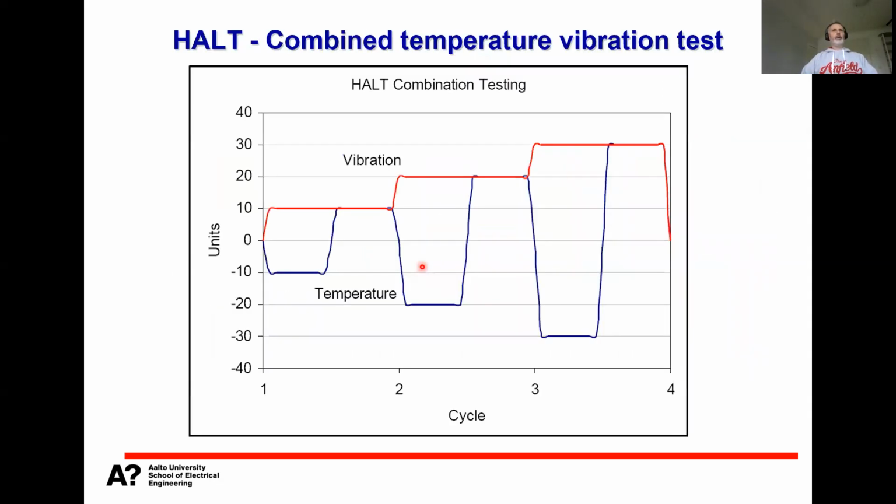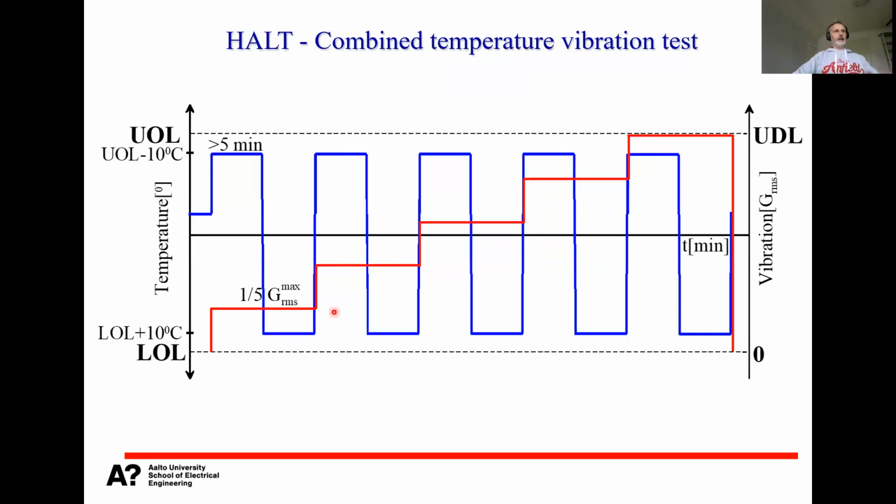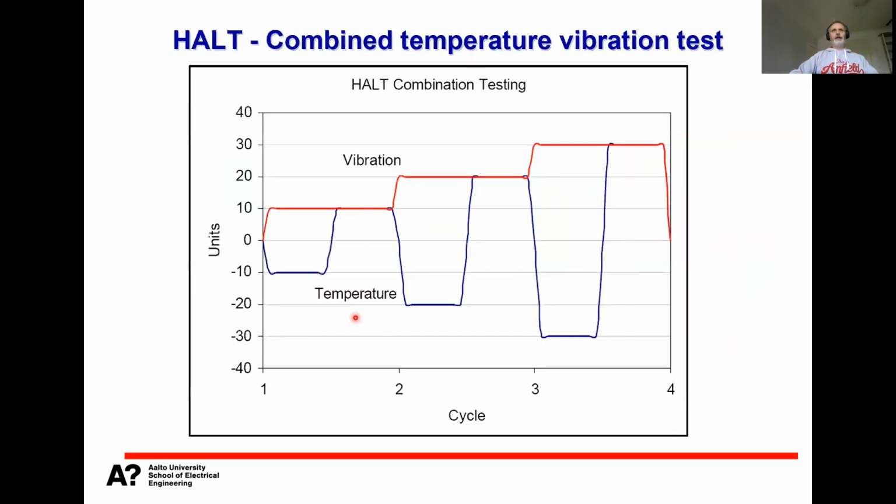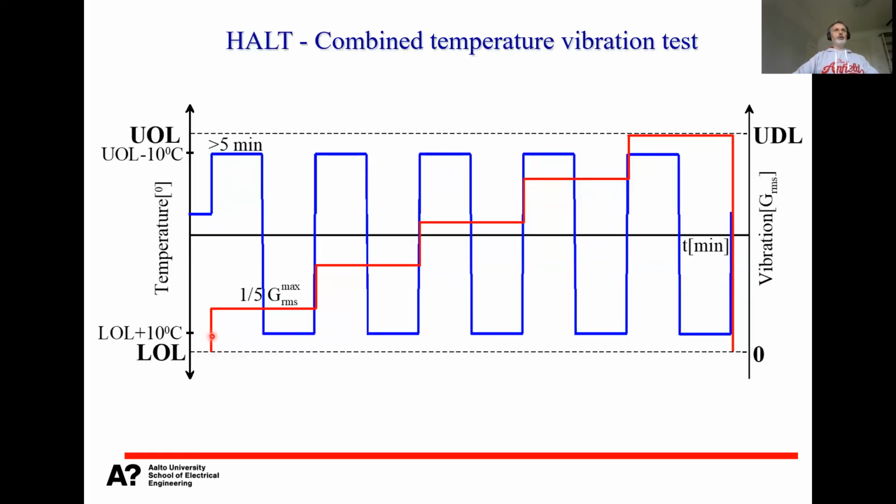There are other ways you can do this. You can simultaneously increase the vibration loading as well as the delta T in your thermal shock, like this. What is shown here is again the classical recipe, but you can do it whatever way. The idea would be that you could monitor the product throughout the whole period. But sometimes that is not possible.